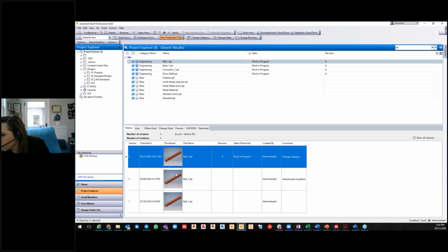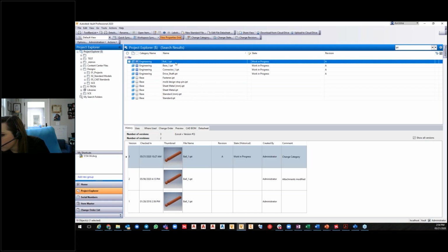Inside the CAD application, when you save it, it takes that home view and isometric view typically, and takes a snapshot of that. So all Vault is doing is reading the thumbnail from the file. It shouldn't be a Vault issue, and if it is a Vault issue, then I will need to look into that a little bit further. But what you can do is just double check.